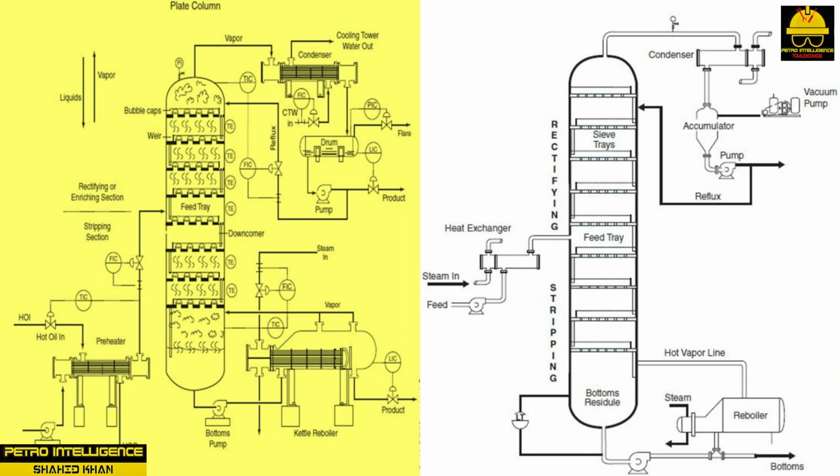Hot vapors pass over chilled tubes and condense. The condensed vapors are collected in an accumulator or receiver. Some columns use the same technique to cool side stream draws off a tower.